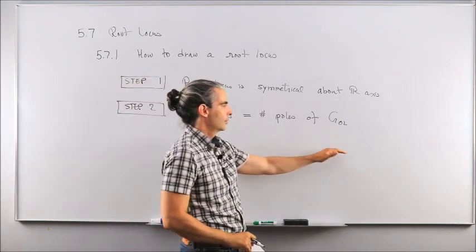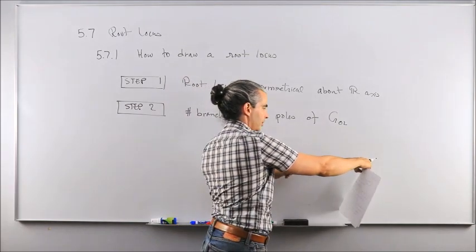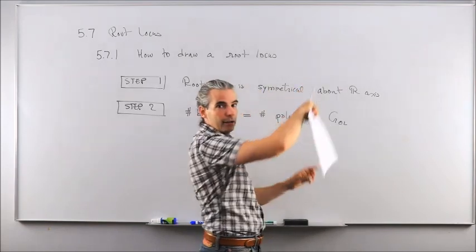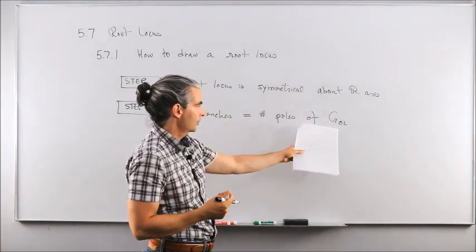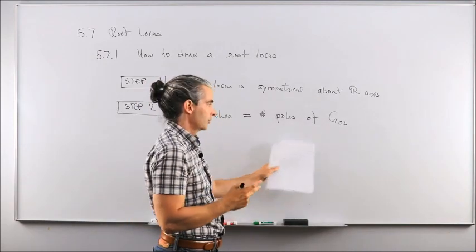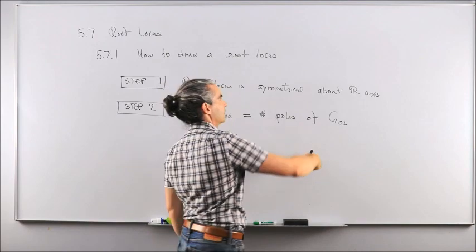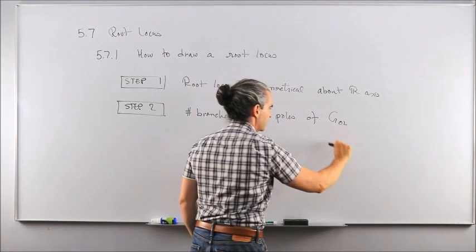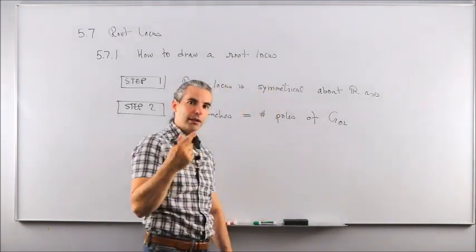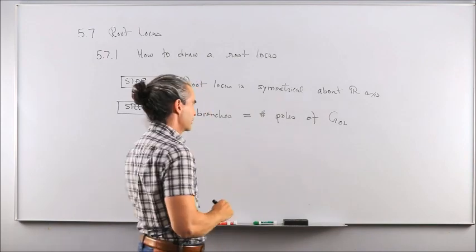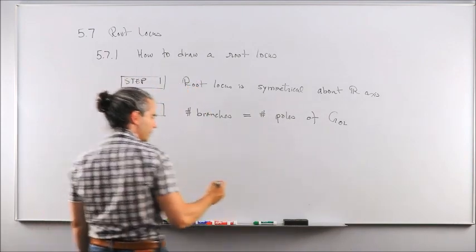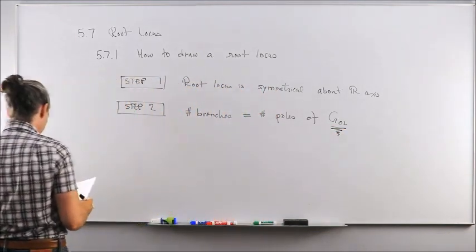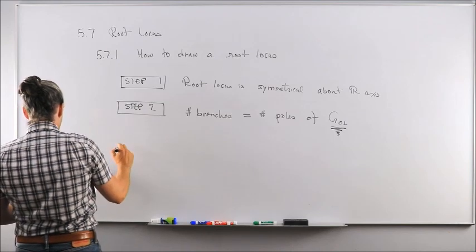In the previous example, where we had the 2 poles, one at the origin, one at -1 for open loop, and they were meeting up in the middle and then shooting up and down. In that situation, we had an open loop transfer function with 2 poles. And as you saw in the root locus, we had 2 branches, or 2 paths, essentially. Okay, because one pole will lead to one path along the root locus. That's all you have to remember. But the key point here is that you need to look at the open loop transfer function. Okay? Step 3.